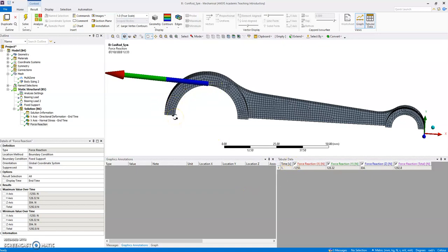So why would we want to replace the load here by a fixed support? Well, that's because it's going to allow us to do more things, to add even more realistic loading conditions, and especially an acceleration to account for the inertia of the conrod.